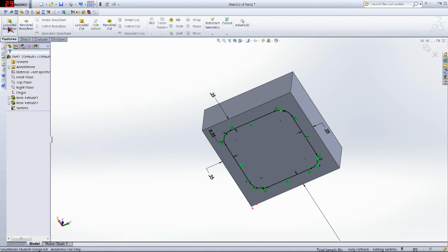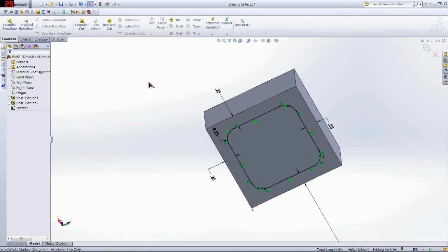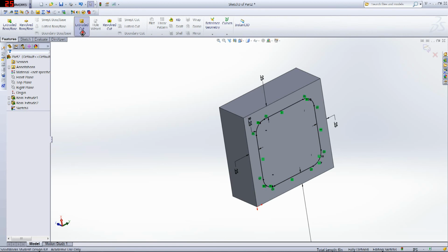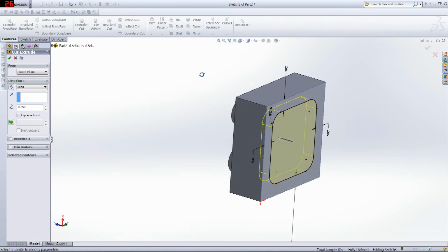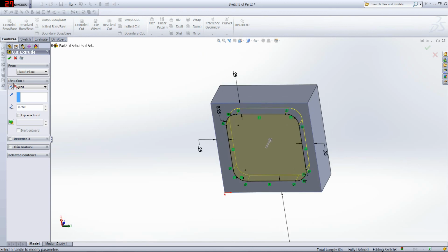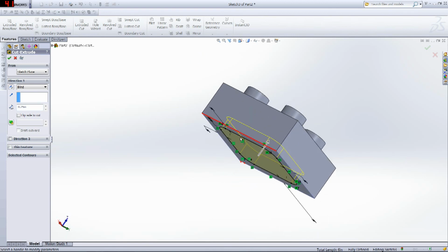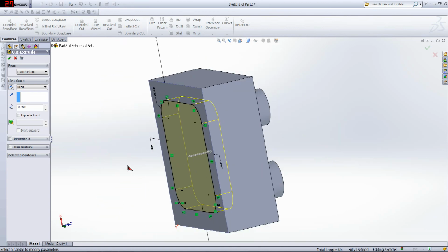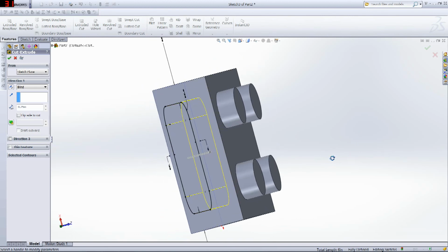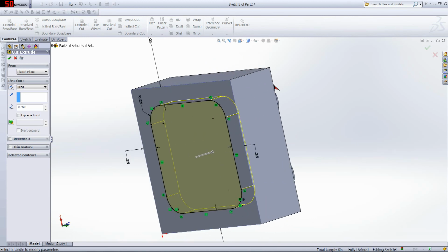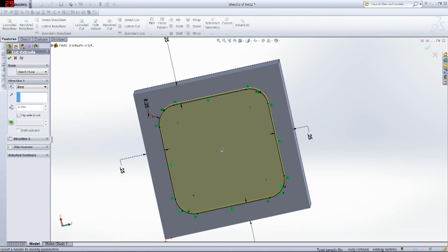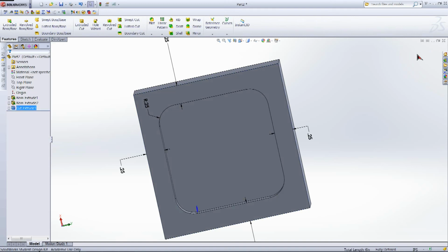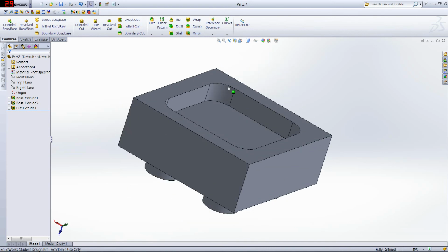So now, instead of using extrude to create material, we want to get rid of it. So you use cut extrude right here. Click on that, and now instead of 0.25, which would be exact for these pegs, sometimes there's some tolerance in the machine that's needed, because maybe your cut isn't exact, and because of this part contacting the top, this distance isn't too relevant. So here you want to put it somewhere between 0.25 and 0.3. So I'll put 0.27 here. Check, check. And now you can see that it's created the hole for it.